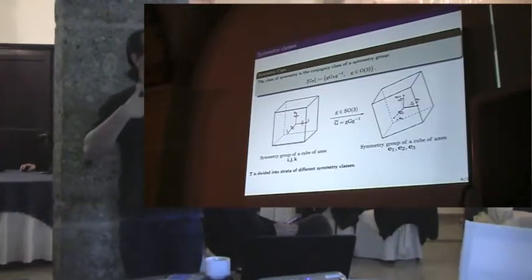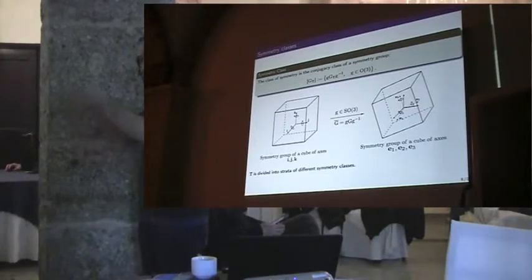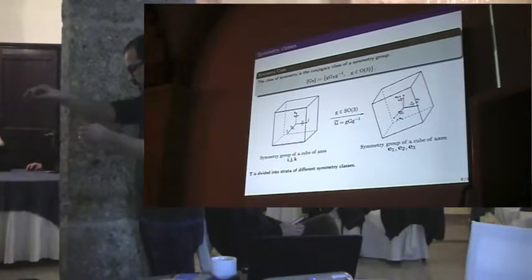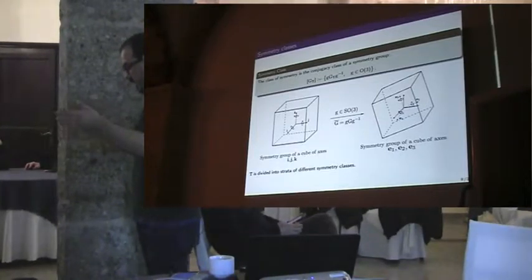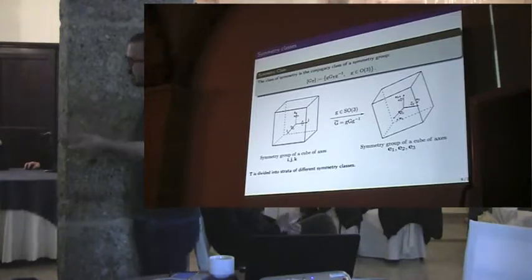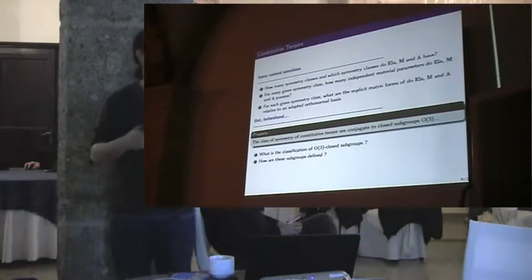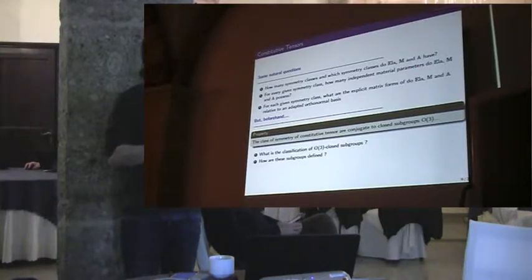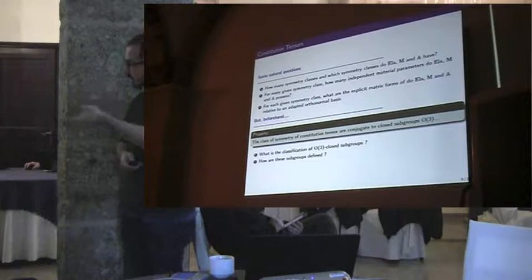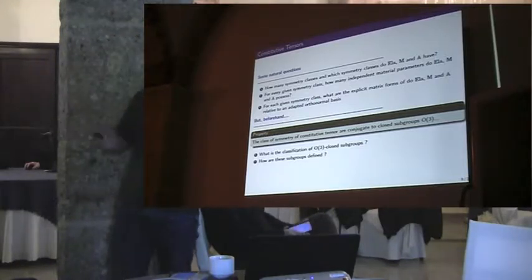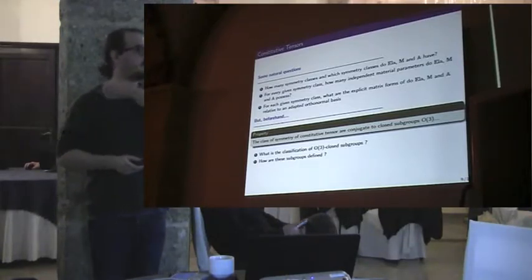So once you have this notion of symmetry class, you want to know for a given vector space that is used to pick up your constitutive tensor, into how many anisotropic systems your vector space can be divided. That is the question, indeed, we have to ask about strain-gradient elasticity, and we have to ask this question for each one of these vector spaces taken separately before putting them together and concluding for the complete constitutive law.